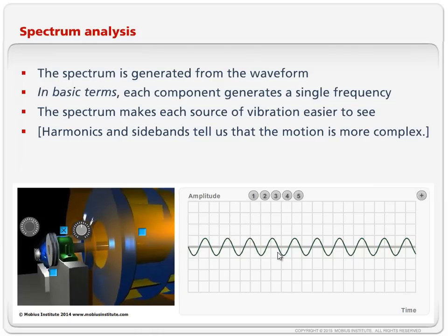It's a higher frequency. Now, in reality, bearings can generate 4 different frequencies, and those frequencies, those signals, if you like, are not normally simple and sinusoidal. We'll talk more about that soon. For now, let's just focus on the fact that we've got a different frequency because, as the rolling elements roll around, the interactions that occur are a different frequency from just the running speed.